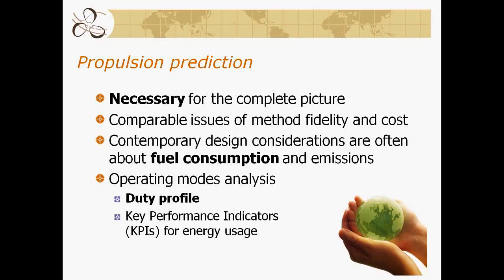And in order to get a good overall fuel consumption, we typically have to describe things by operating modes and a duty profile. And we use key performance indicators for overall energy usage. And we'll show a simplified version of a key performance indicator here for our little case study.